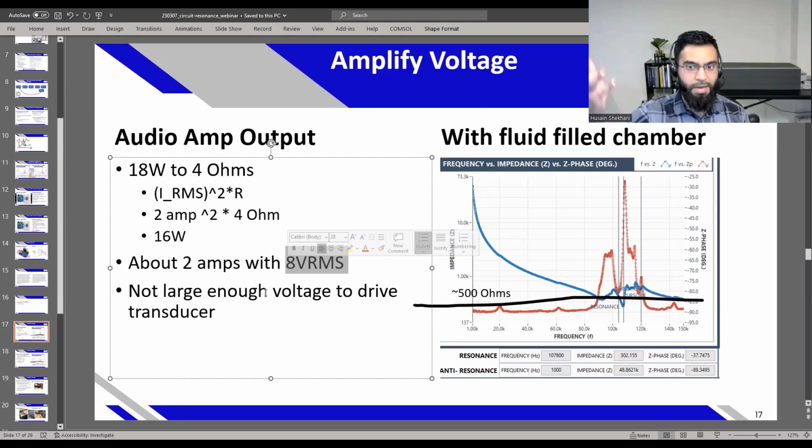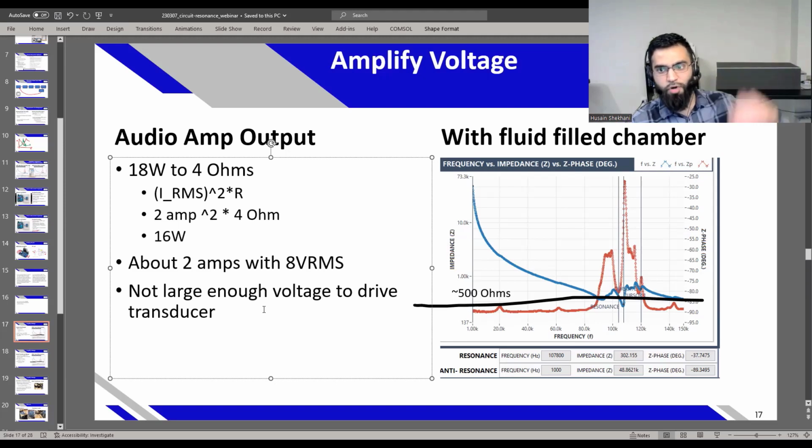But sometimes there's a step-up voltage, like you can provide 5 volts and there's a DC step-up to 20 volts or whatever. But in this case, your supply voltage limits the maximum voltage you can do. So I had 7 volts, so the output would be approximately 2.5 volts, because there's some drop, right? So the output voltage was swinging between about 2.5 volts and minus 2.5 volts, which is kind of small.